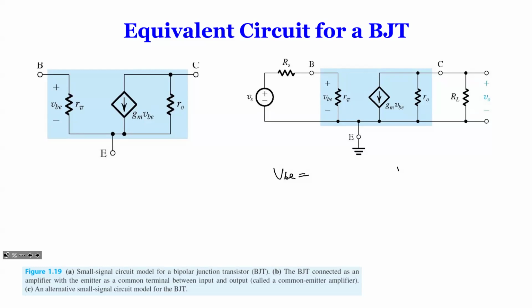Yeah. Now, BJT is a device. It's an amplifier, in particular in this class and 430. Of course, when you get to, say, 584, it's no longer an amplifier. It's actually a switching device. But yeah, amplifier is the name for MOSFET and for BJT. For now, they're amplifiers. Okay, so let's look at the input side. Even though I said use nodal analysis, here you actually have to do a loop analysis, but it's not that difficult. What is VBE? Can we do it together?